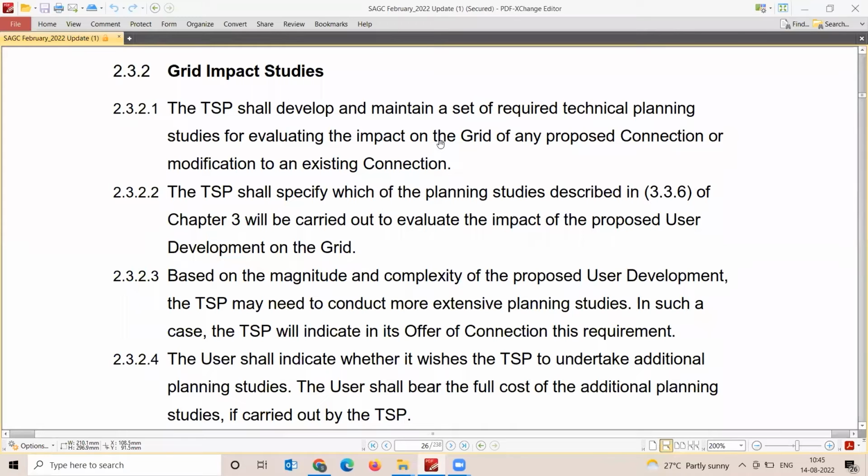Shall I apply the same grid code which I applied in 2006 to 2022? Absolutely not. Grid code compliance study is an ever-evolving requirement. That's the reason the transmission system operator is also trying to upgrade it on a daily basis. LVRT was not a requirement for wind farms before 2006-7 in India. That's why type 1 and type 2 wind turbine generators were quite popular in India before that. But after that, LVRT was made mandatory, thanks to probably a blackout somewhere in the world. Why was that imposed in India at that time itself?